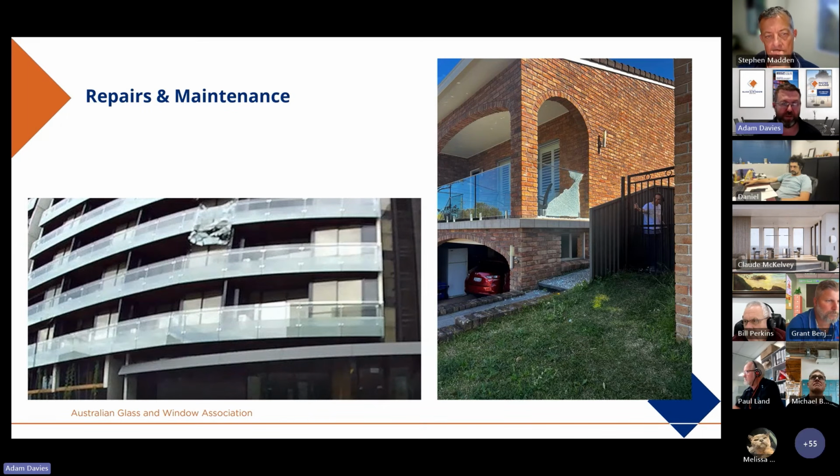So the general advice that AGWA would provide is, where possible and appropriate, you should comply with the latest relevant standard, particularly if there's been a stringency increase. So if you are able to easily select and install glass into this scenario that does comply with the current provision 12, you would do so. In some instances, this may not be possible. For example, an infill barrier may not have the channel width to support the thickness of glass that might be required. Then it would come down to an individual risk-based approach where, for instance, if I was replacing